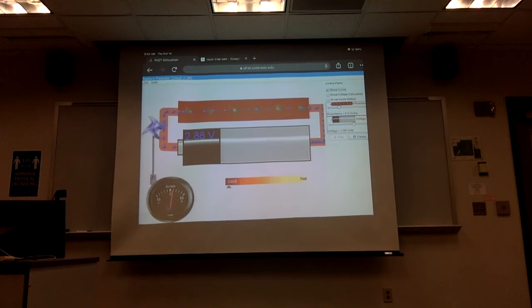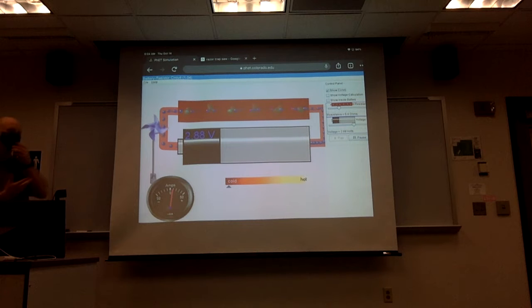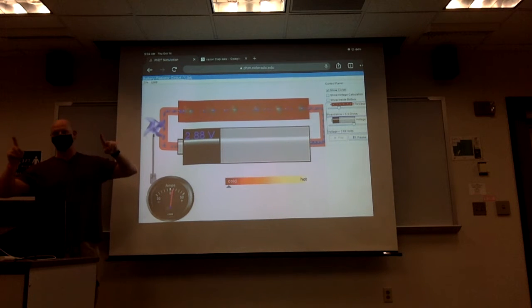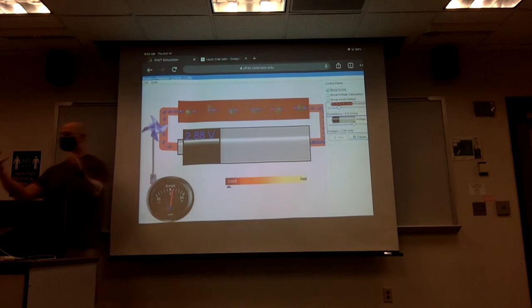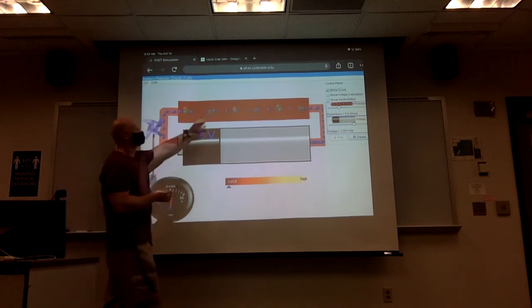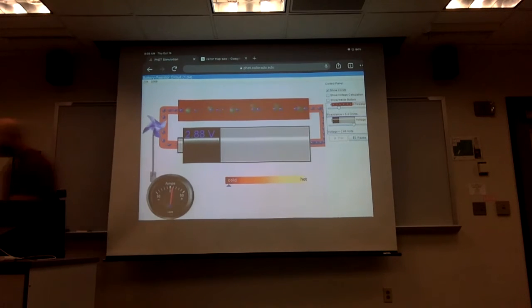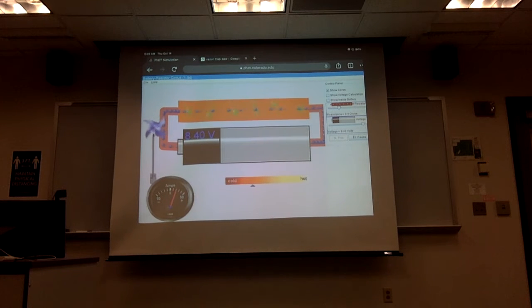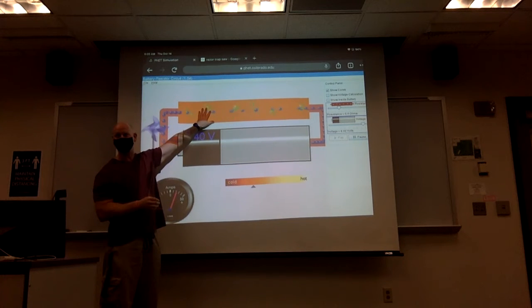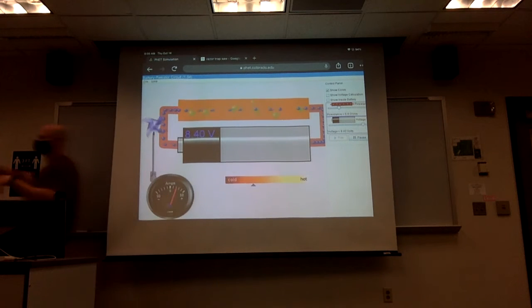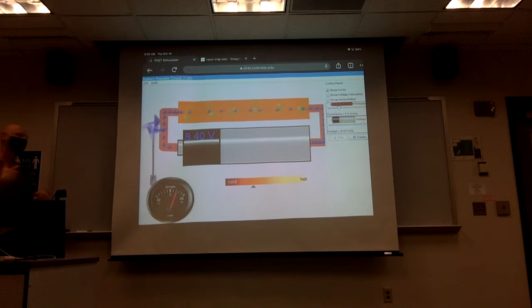And we know from kinetic theory from 205 that the greater that they oscillate, i.e. the greater the kinetic energy, the higher the temperature. Remember in 205 we said that temperature and kinetic energy were basically the same thing. So temperature is simply a measure of the kinetic energy, which means if I crank up the voltage, these things are going to oscillate more and more rapidly due to all these collisions, which means this thing is going to get hot. As this thing gets hot, that energy is then going to be dissipated out to the rest of the world via heat.